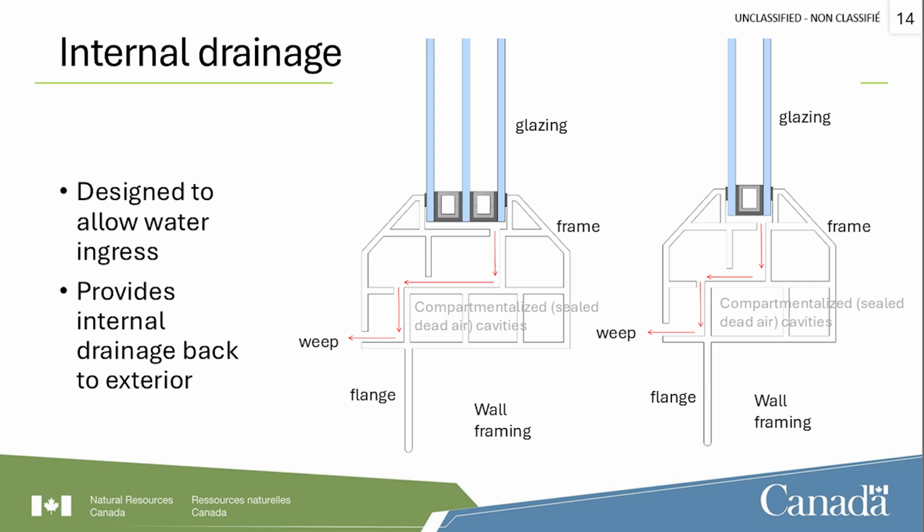If the wind was to blow in this opening, how much wind could actually blow into the building? Very little. So it pressurizes the cavity so the water can drain out, but it doesn't allow wind to blow water back in. And if it does blow in, it loses momentum. So if the water even pushed up to this point, it would never make it up here to make it inside the building.